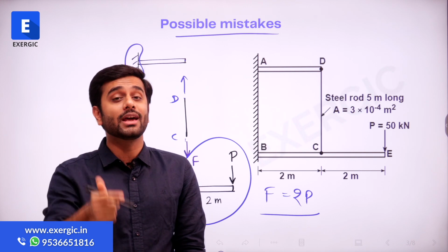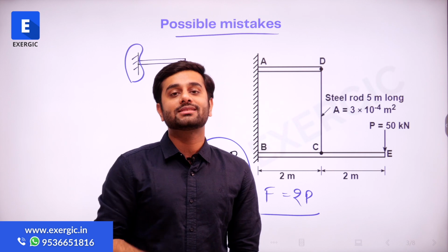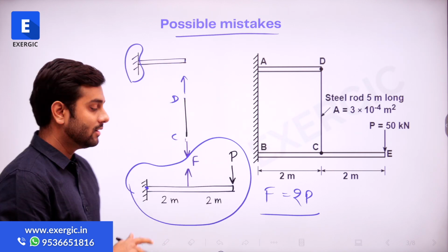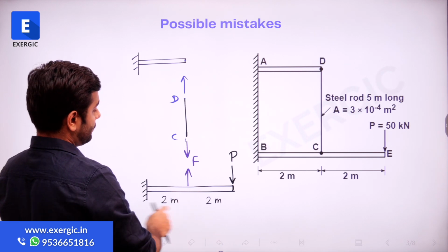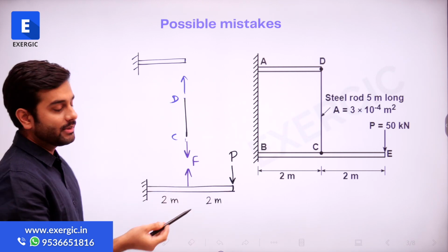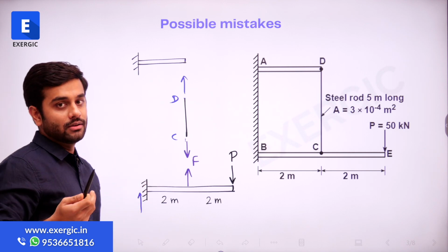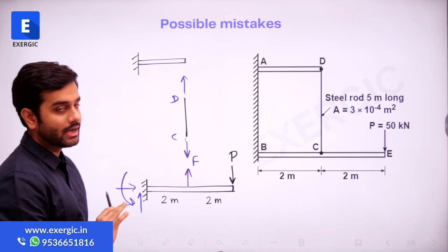It's very important here because this is not a statically determinate beam. It's a statically indeterminate beam. How can I say that? Let us have a look at the free body diagram. If I draw the free body diagram of this specific part here, as we know, in case of a free body diagram, when we remove the fixed end, we get 2 different forces and a moment, right?